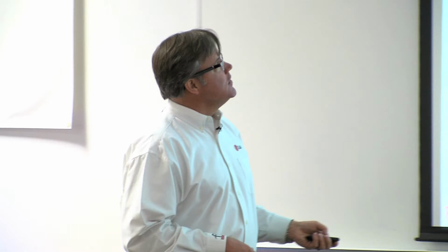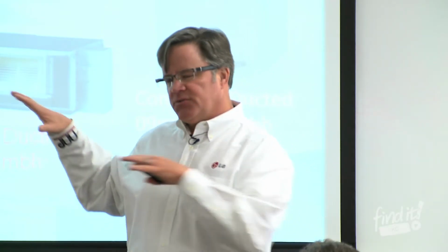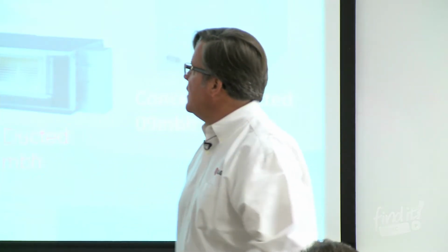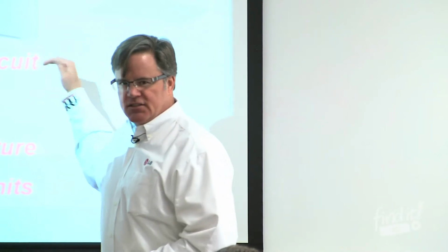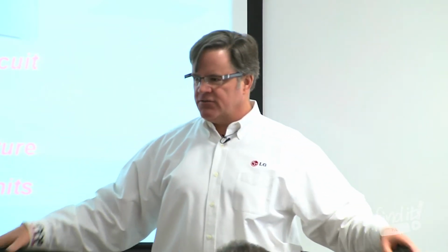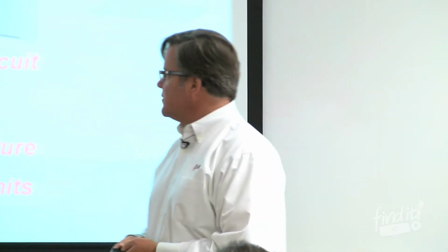The reason why we draw a distinction between this duct-free side and what we're here to talk about today, and that's the bigger VRF equipment, is they communicate differently, and this is true for all manufacturers. If you want to include them on a BMS system, it's going to be a different set of criteria that you're going to have to go through. So that's why there's always a line in the sand between the duct-free split stuff and then the VRF stuff, which we're here to talk about today.